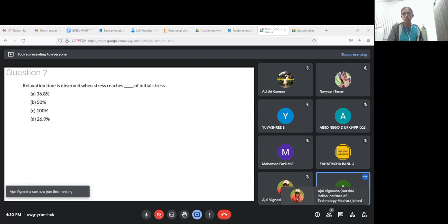What is the equation that you use to define an exponential decay in terms of y and x, maybe? When you give an instantaneous strain, say epsilon naught, your stress, as I mentioned in the previous slide, slowly starts decreasing in an exponential manner. And this is how you define an exponential decay: sigma equals sigma naught times exponent of (t naught minus t) by tau.